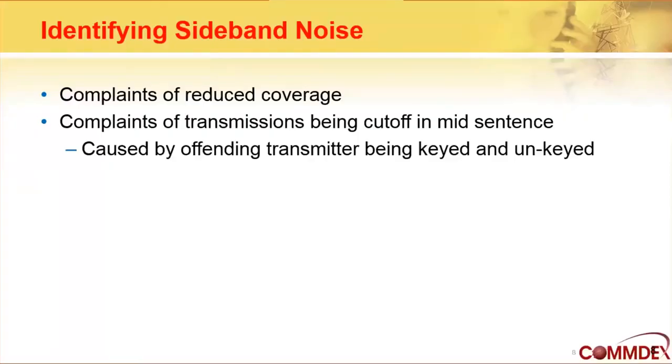Well, how will we know if we have sideband noise? If you're listening, you'll hear complaints of reduced coverage, and you will hear transmissions being cut off in mid-sentence, because every time a transmitter is keyed, it will walk on top of the receive frequency, and you'll hear people complain about that.